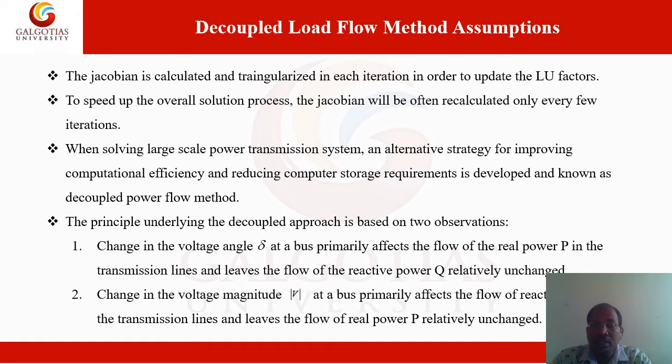Second assumption: a change in the voltage magnitude at any bus primarily affects the flow of reactive power in transmission lines, and there is a negligible effect on the real power, so generally we consider it unchanged. Using these assumptions, the voltage magnitude depends on the reactive power, and the angle depends on the active power. So as you know, in the Newton-Raphson load flow solution we solve the voltage angle correction factor and the voltage magnitude correction factor simultaneously.